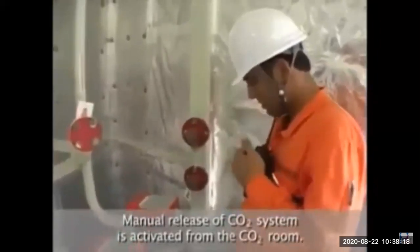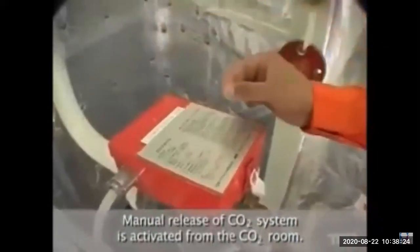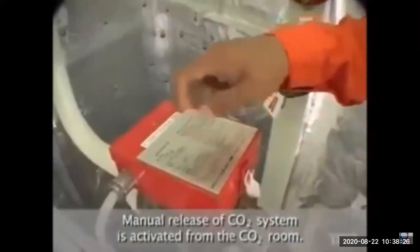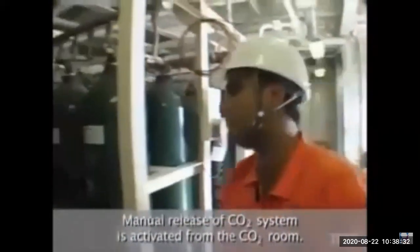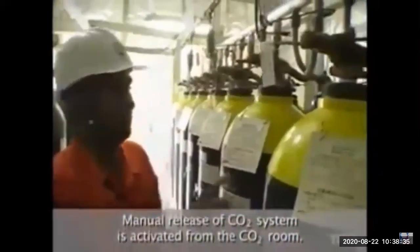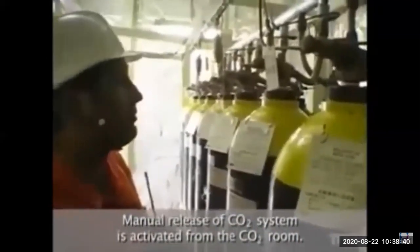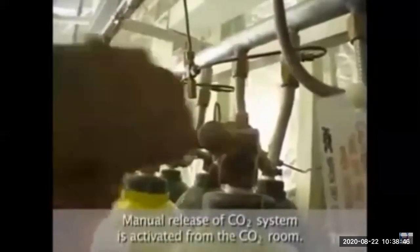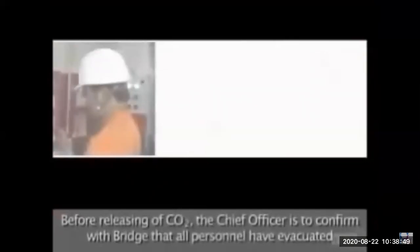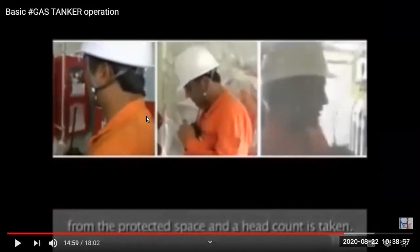Now, if you want to do manual release, there is a button in the CO2 room. Open the box and the pin, and then rotate the valves. And then you go to each bottle which you want to release, and by that box release, remote release is deactivated. So for manual release, you open this pin, put the plunger, and the CO2 will be released. Finally, we flush the lines to confirm that all personnel have evacuated from the station, so that we can know the bottle is fully empty.